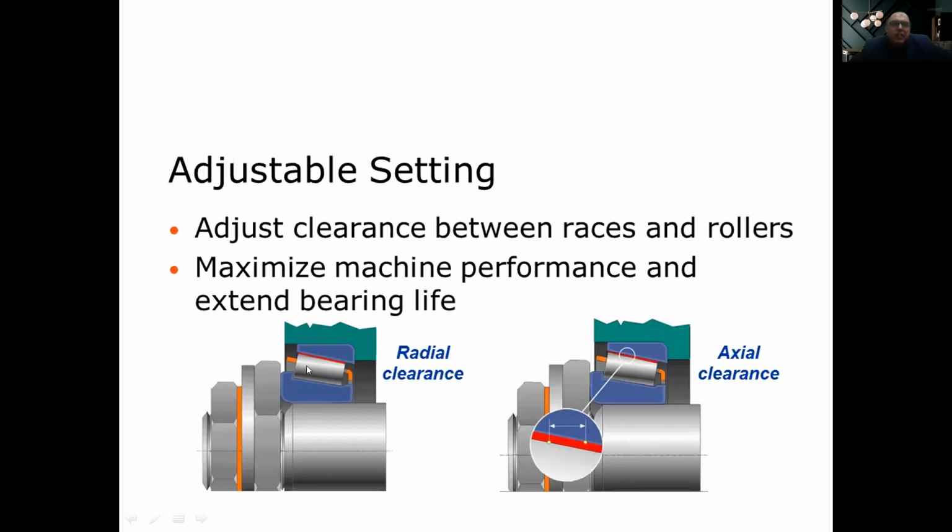Typically, around the bearing where you have a cage, you would put a material which will be a matrix, and it will contain some kind of oil or lubricating material. When the bearing is running, the matrix will release that lubricating material. But you can do that only in slow to medium speed and low load applications. Wherever you have heavy load, you will require external lubrication like grease or circulating oil. So in light duty applications, you can use self-lubricating bearings.